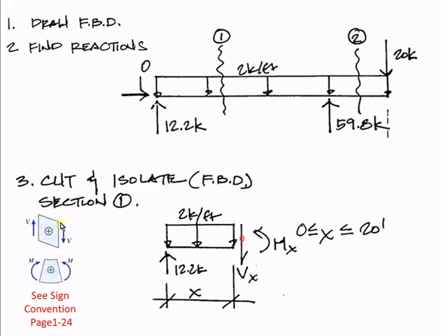On the right-hand side of that element, the internal force being replaced by the remainder of the beam that's not shown is pushing down on that element, and on the left-hand side it's pushing up. Because we're cutting our section here and keeping everything on this side, on the right-hand side of the portion we're looking at, we draw our shear reaction consistent with this sign convention, and that's why our shear reaction is shown acting down.